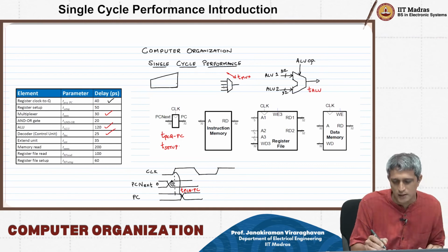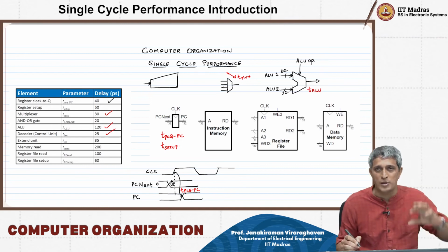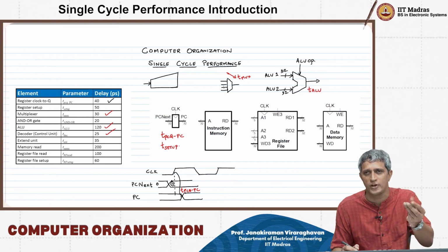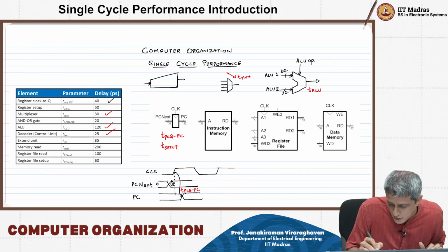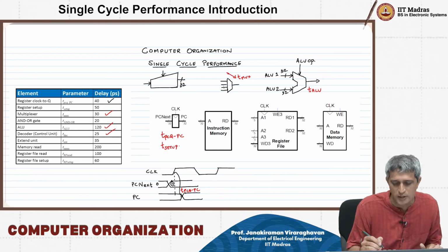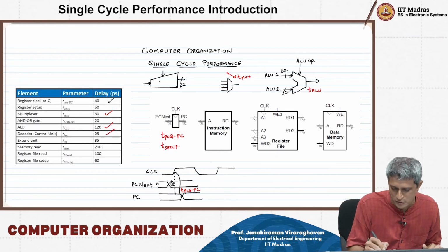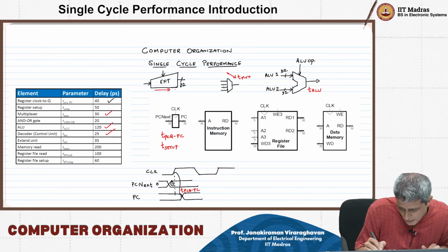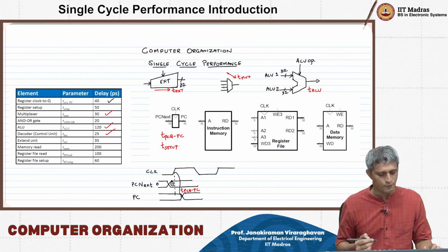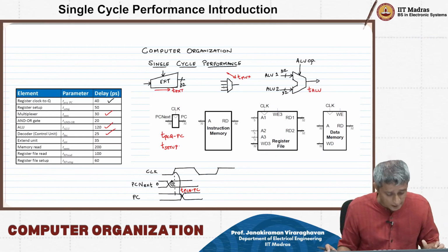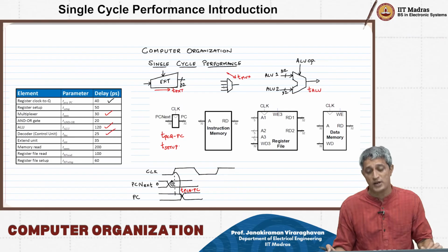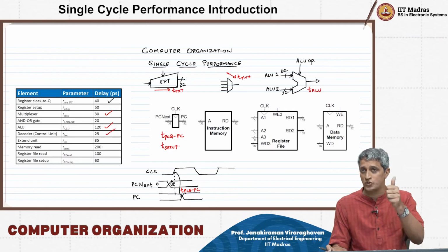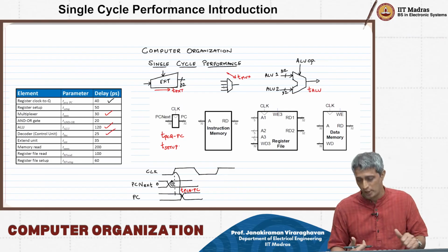Okay, we are drawing it this way because data is coming in as some 12-bit, 20-bit, some very small bit format, but it is going out as 32-bit. And there is something here which is going to help you decode this, right. So this delay is what we are calling T EXT, right. Then you have the memory read. Now we had two kinds of memory. One was the instruction memory and the other the data memory, okay.